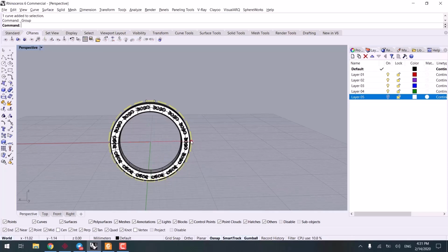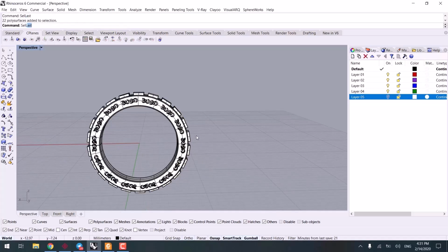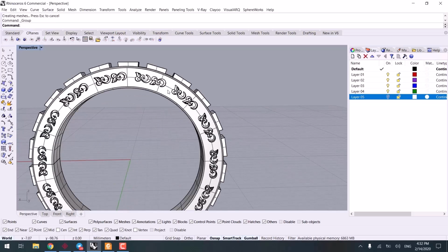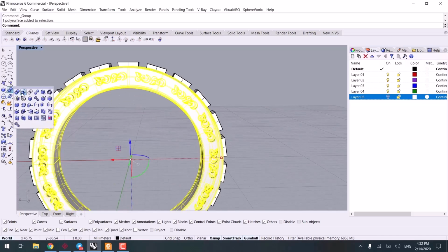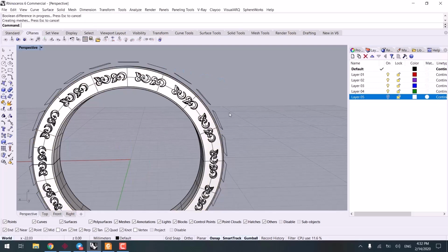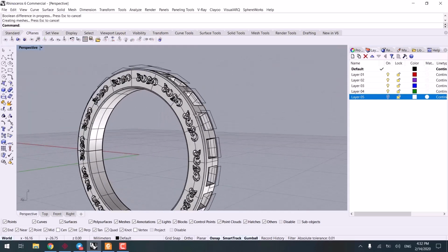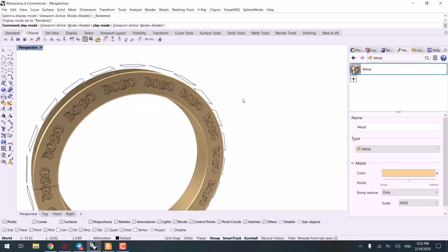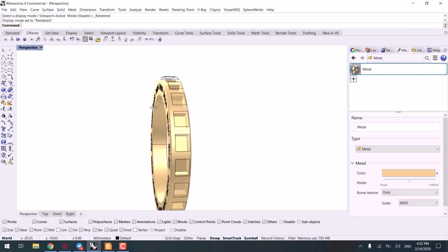Again, in perspective mode, hold Alt and Shift, change up the scale, hold Control as well, select again, cap, close down the openings, and Control G. Now Boolean difference to cut the group out of our ring. And as you already know, finally we can add the material and we would be all done with our model.